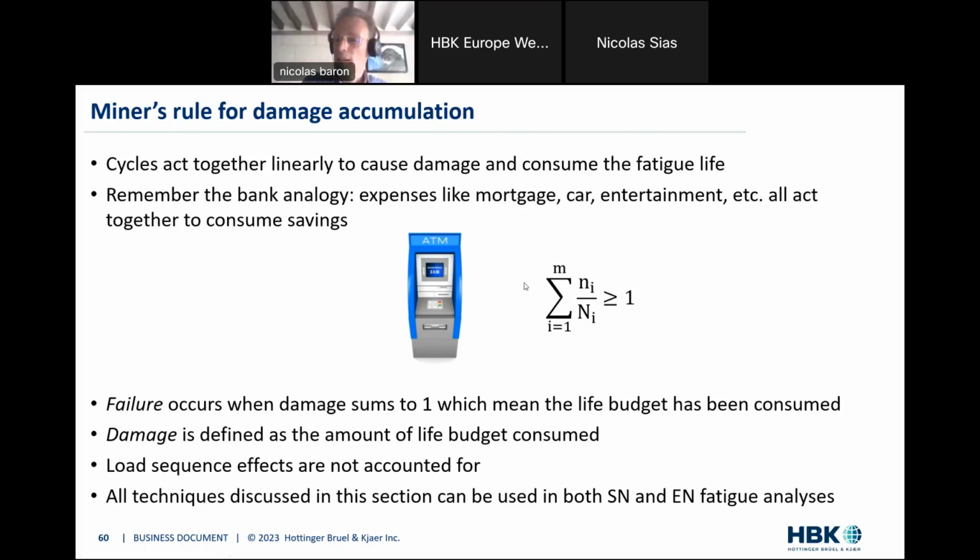But in reality, we see that Miner's rule applies very well in real life. So even though theory might be more complicated, practically, we know from years of practice that Miner's rule applies very well. So don't bother yourself with this complication; you could if you're doing research and things like that, but if you're practical, if you're an engineer working on your design, you can safely assume Miner's rule works fine, and this will be the case in most of your cases.